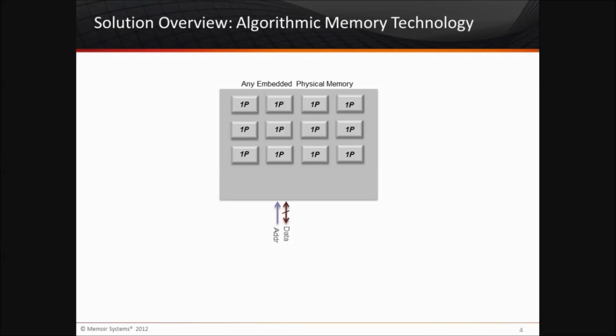Imagine this memory was 12K deep and 144 bits wide. I just took some random example here. The physical compiler would break this up into a bunch of banks. And if you run the clock at 500 megahertz, you would get exactly 500 million operations per second, and no more. You could be lucky, and you might access data from a different bank, and you might get more accesses. But embedded memory is built for worst case, and so you get no more than 500 million operations in the worst case if the clock here was running at 500 megahertz.